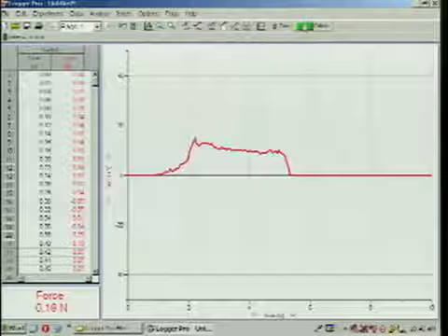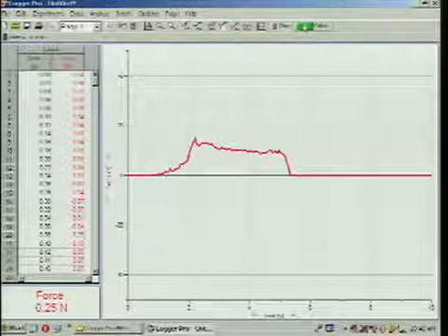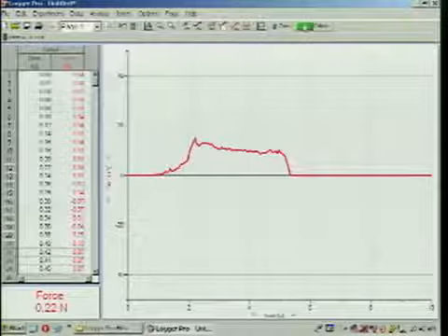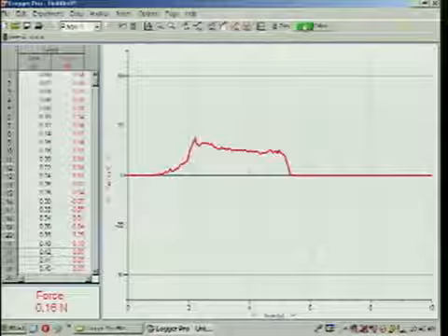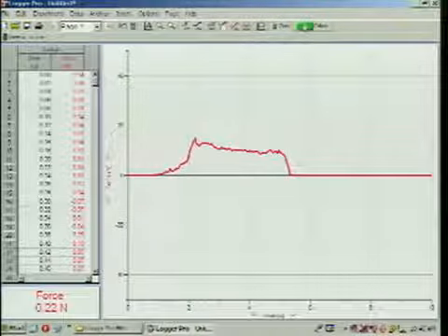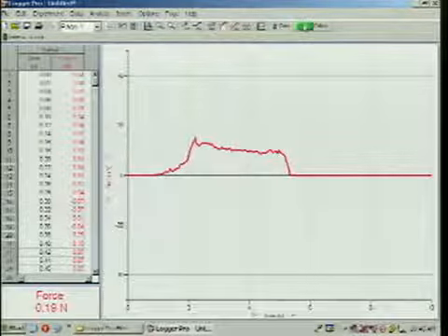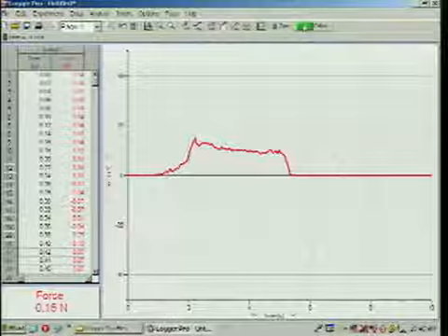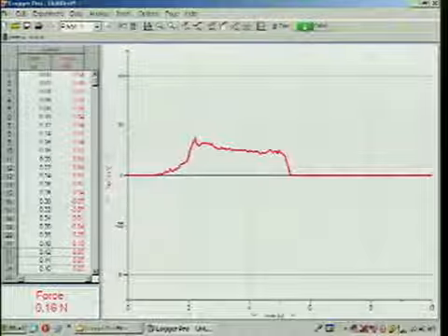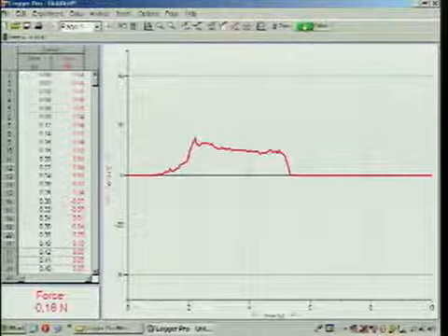You can also see that I had to keep increasing the force to the point where it started slipping. And then the static force, which is what's being measured up here, was increasing as well to the point where it started sliding. Static force is only what it needs to be in order to keep the relative surfaces from slipping. Then once it starts slipping, it turns into sliding friction, and it's basically a constant.